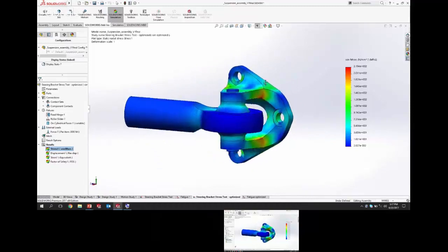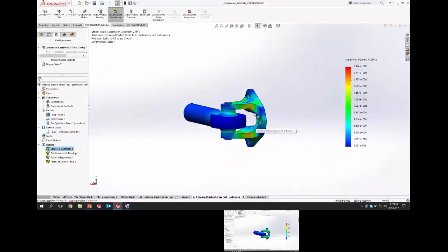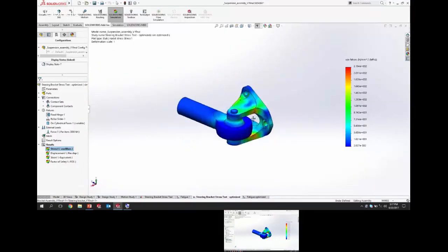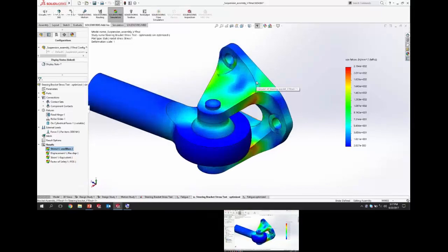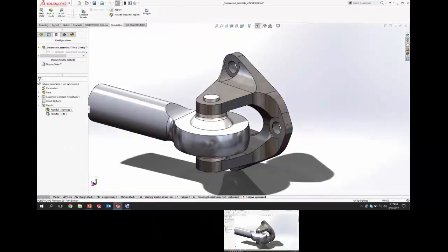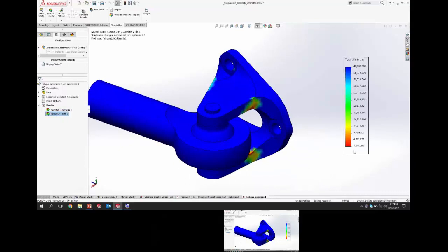Okay, we still have the same kind of stress hotspots in the same place, but who would think? When you remove some material, make it a little more flexible, get the stress distribution or strain distribution move through the model, the stresses actually go down. So our fatigue life ends up being over 1 million cycles, 1.3 million cycles. So now we're starting to actually get over-designed by removing a little bit more of the material.